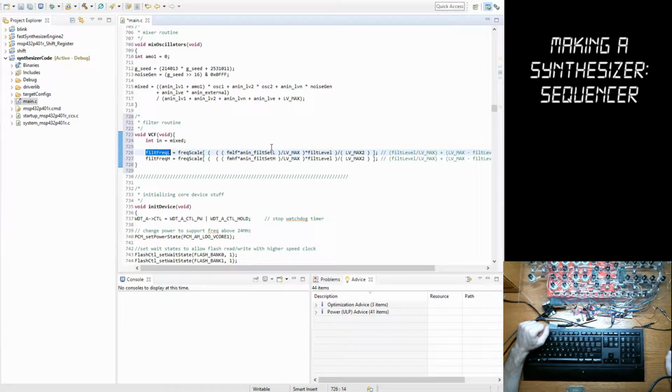Currently this is so that as you turn the knob, all the way low means you're basically nearly at 0 hertz. And all the way up goes right to about 20 kilohertz. So it's the full hearing range that a standard human should be able to hear. And this high frequency is the same thing. The only difference is that it just goes to a different filter, a high pass filter.